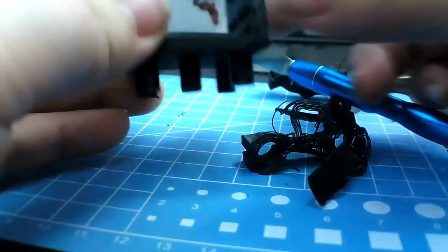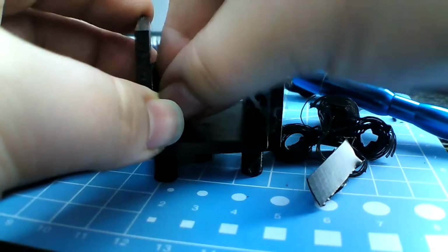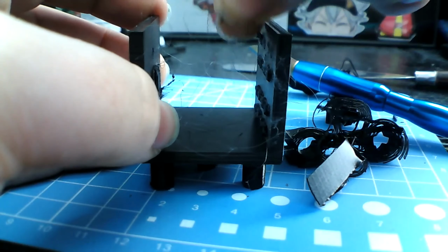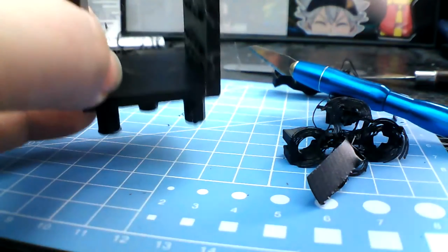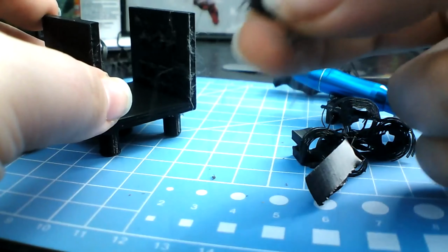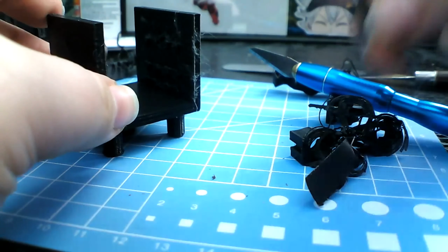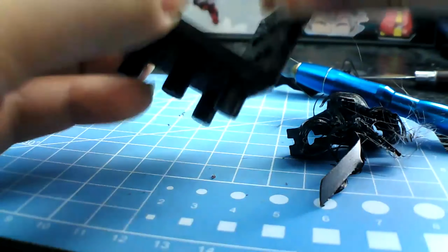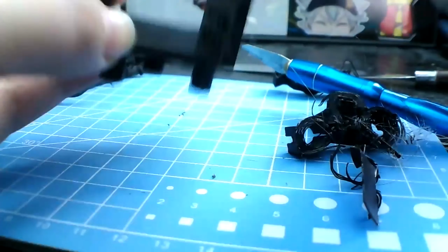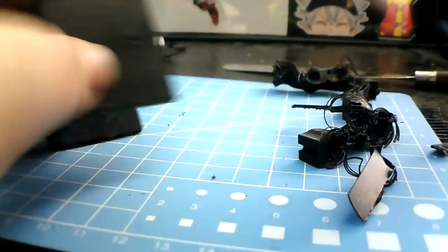Let's see. Also, I don't know if you guys can tell, but there's a bit of stringiness on the print. This is with a pretty cheap PLA material. Usually the cheaper the PLA, the lower quality it is. It's kind of hard to tell, but there are little stringy pieces. This also happens if the printer's too hot. I think the settings I have are a little too high for this, so it causes that stringing, but the strings are pretty easy to take off. So I usually just keep my settings the same.